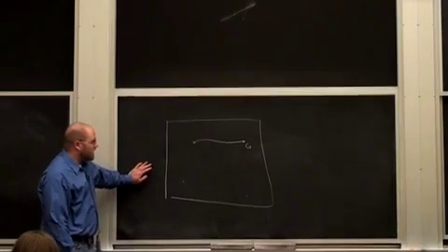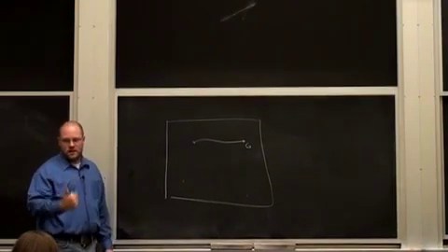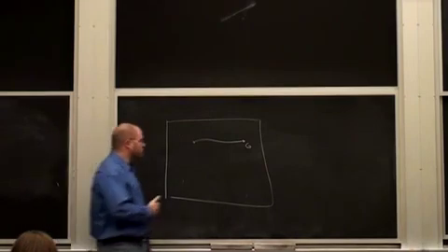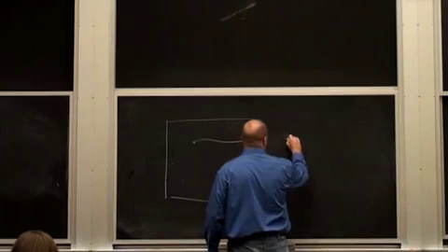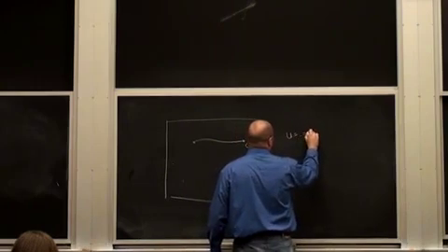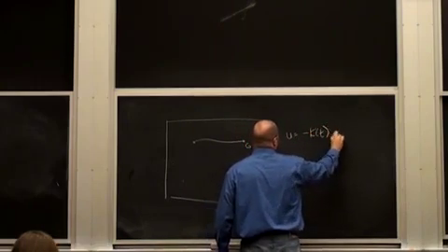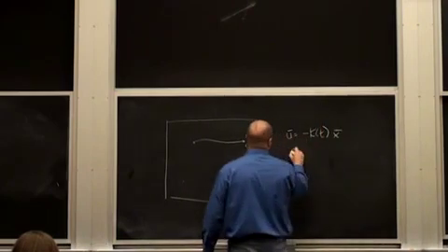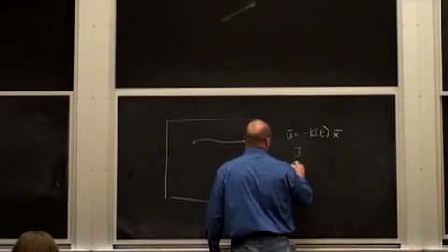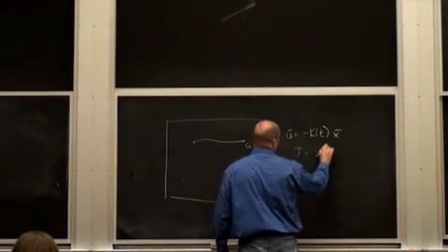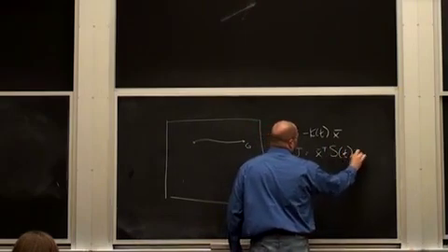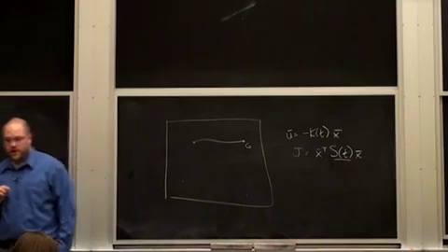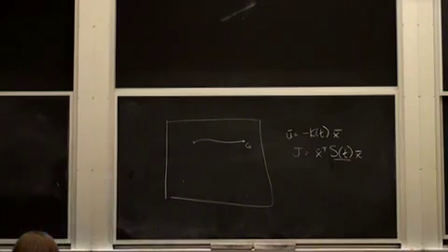The great thing about that is, first of all, that it will locally stabilize the trajectory. But second of all, because we are given both u equals some time varying feedback policy, we're also given an estimate of the cost to go, which is in this time varying matrix, from the Riccati equation backwards.